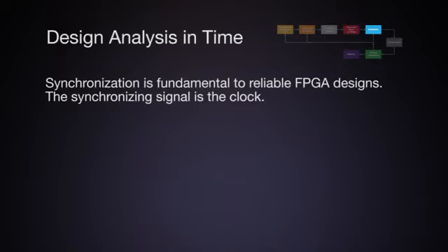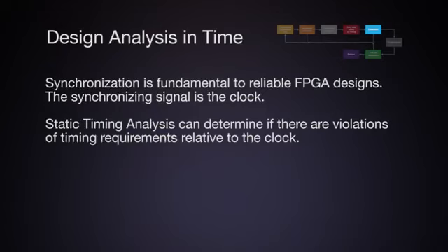Synchronization is fundamental to reliable FPGA designs. The synchronizing signal is the clock. Static timing analysis can determine if there are violations of timing requirements relative to the clock. It is the primary tool for achieving timing closure, a necessity for any and all FPGA designs.